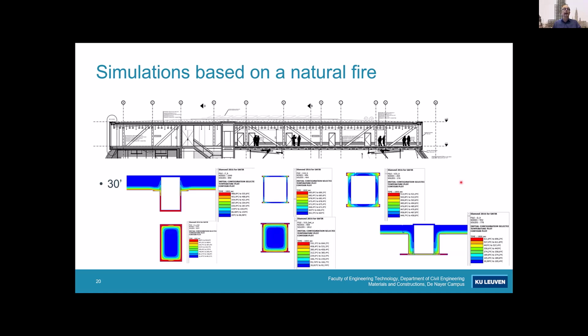So okay, and then what we thought was, let's insert concrete. Instead of dismantling everything, let's drill a small hole in the tubes and insert concrete. So we pump a grout into it, and we use the grout only as a thermal part, not as a structural element. In the mechanical part, this is an insulation, and then we can start to calculate what the temperatures are. And you'll see that only in the tips are we getting over 540 degrees Celsius. So it seems that it could be a solution there.